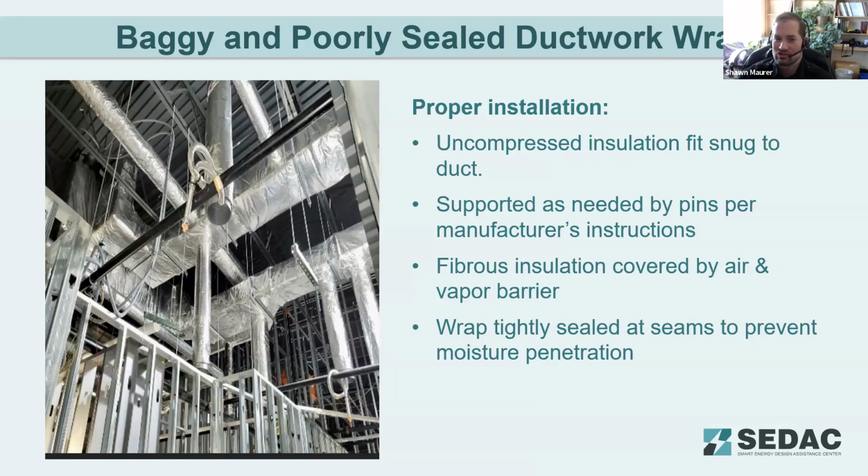And so you do have a leakage class generally, depending on what the air pressure in that ductwork is going to be, that must be met. And so whatever sealing needs to be done to meet that leakage class needs to be done before you install the insulation on the ductwork. If you don't seal the ductwork on the supply side, you can have a pressure issue where air leaking underneath that insulation causes it to billow off the ductwork. And you can actually tear the insulation, pop it off of any pins or fittings that are holding it in place on the bottom of the ductwork. So yes, proper sealing must be done beforehand.